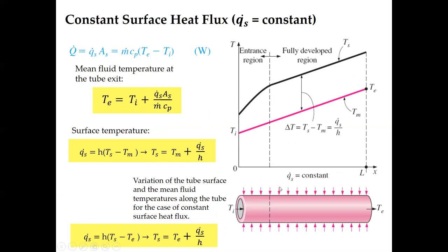So let's say this is a circular pipe, and we heat it with Q. If we heat the pipe by applying heat flux on the surface, we can also monitor the surface temperature. Of course, that is different. In this case, you add heat flux on the surface, and the surface temperature will increase. But you don't know it, though obviously we can calculate it, and it causes the fluid temperature to increase. So based on this graph, let's say your inlet temperature starts from here, and then the temperature is going to be higher because we add Q on the surface of the pipe.